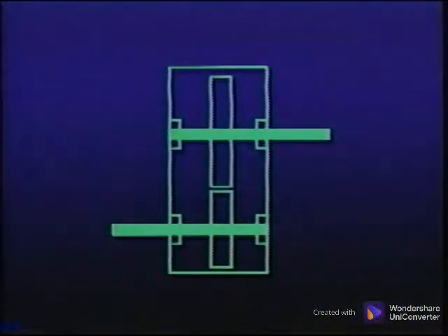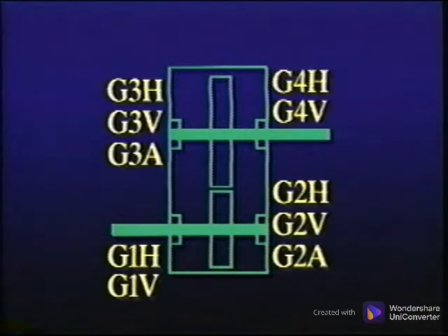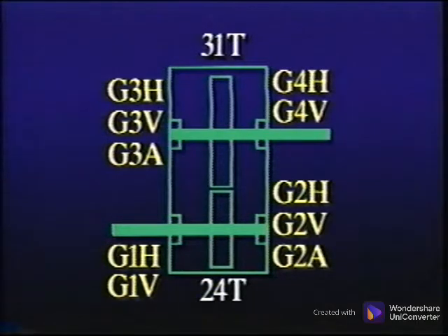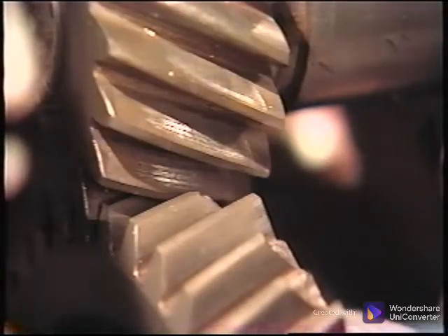Another helpful tool is a simple diagram of the gearbox showing each shaft, the measurement point locations, and the gear locations. It is very important to know the exact input shaft speed and the number of teeth on each gear. These will help in determining exact gear mesh frequencies and other indicators. We expect to see the gear mesh frequency for the gears, and when the gear or meshing action is not correct, the amplitude of the gear mesh may be affected.